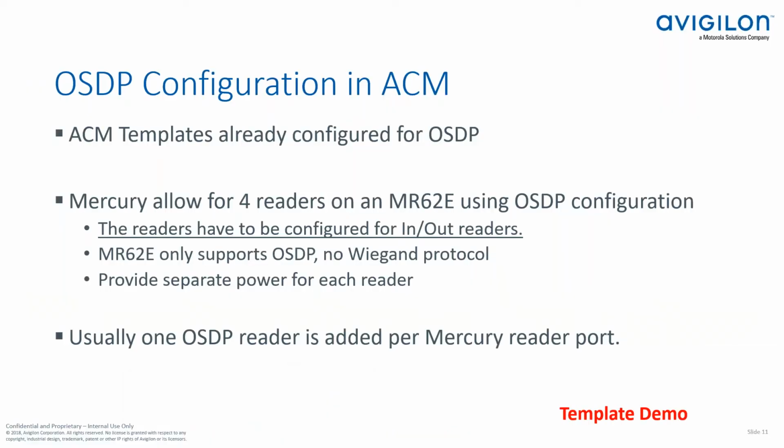So that's the template, pretty easy. If you're installing a new system and going to deploy 64 doors, using maybe an HID RP40, for example, or RPK, or a reader that has mobile capabilities, OSDP is going to come enabled by default. Wire like that, go into a template and just deploy 64 doors, and they will already be configured for OSDP address 0. Super simple to configure at that point. Okay, and it does provide you longer distance for the wiring, so it's a pretty good setup.